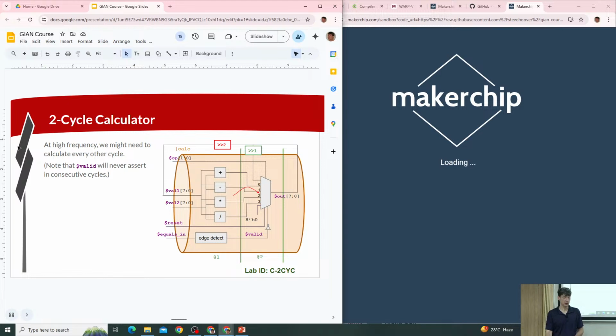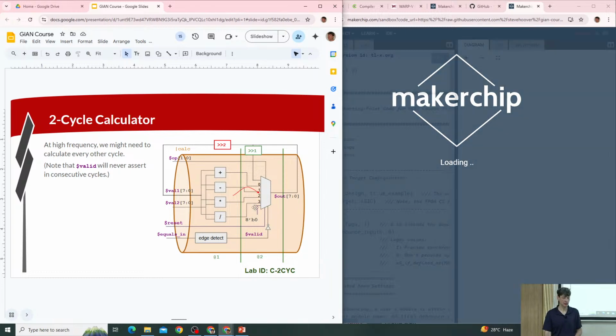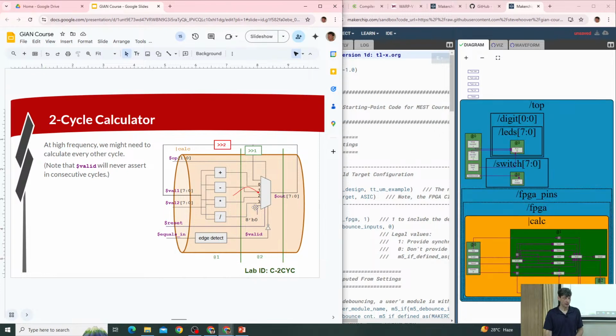Maybe we only have time to do the arithmetic operations in one cycle, and we need to save the multiplexing for another cycle, just as an example. So obviously, if that's the case, we can't do back-to-back calculations every cycle. We can do back-to-back calculations every other cycle. But we might be constrained. We might have to separate it across 2 cycles and limit the throughput.